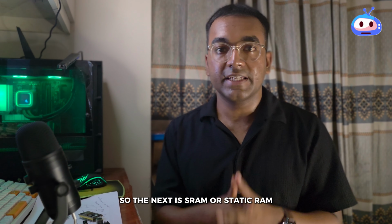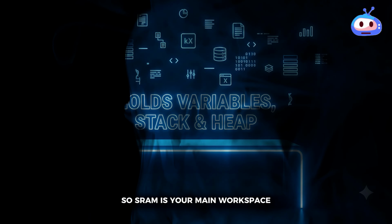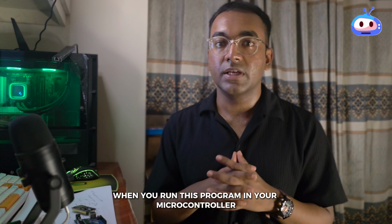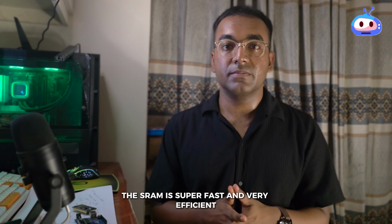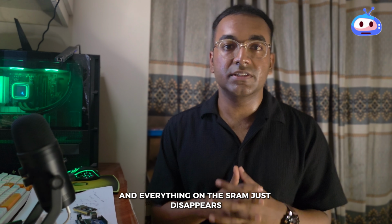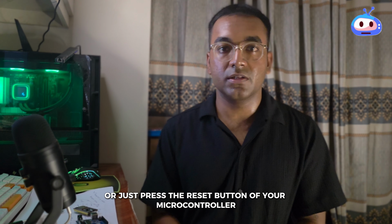The next is SRAM, or static RAM. Think of it like the desk you are working on. SRAM is your main workspace. This is where all your variables, the stack and the heap stay when you run a program on your microcontroller. It's the desk where all the active things happen. SRAM is super fast and very efficient, but it's volatile. You turn off the power and everything in the SRAM just disappears. That's why your variables reset when you turn the board on again or press the reset button of your microcontroller.